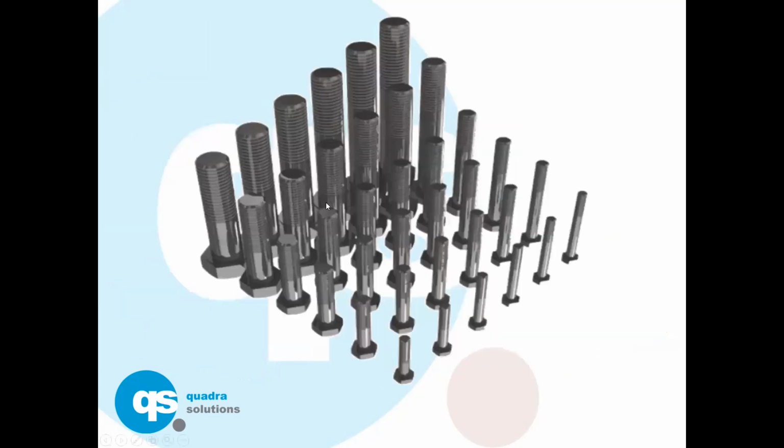Now, there's our number of files. With an iPart, you've got the master, the factory, the parent iPart that contains the spreadsheet. And in this particular case, that particular iPart can generate 36 different sizes. So there's 37 in total. There's 37 files that you potentially have to manage on your hard drive, or through Vault. But there's 37 things: the parent file and all the children, the factory and all 36 products of that factory. Granted, if you only use one size of that bolt and 35 sizes just never get used, you've only got 2 files on your hard drive.